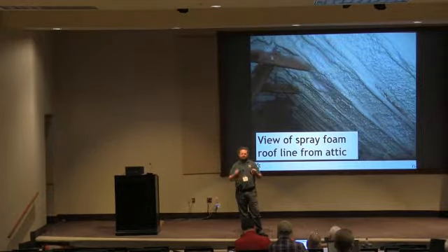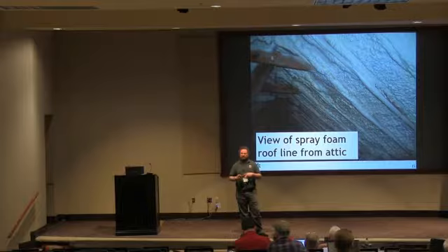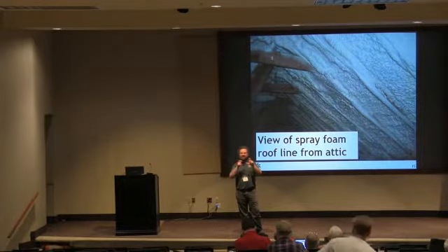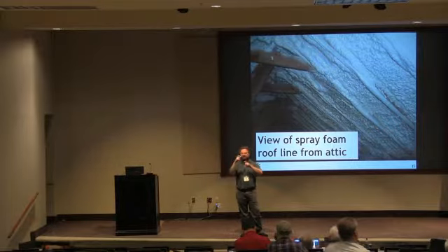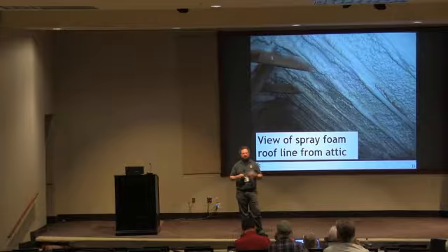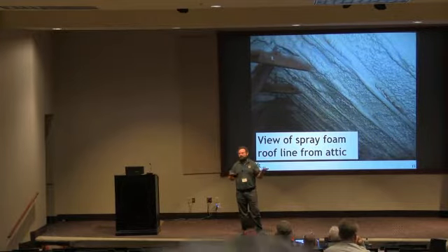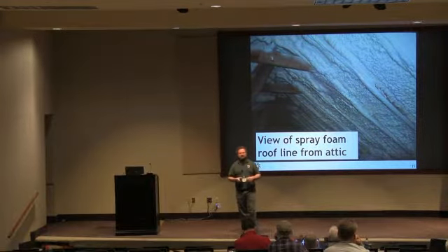And so if you have leakage on the return side of your ducts, it's not as big of an energy penalty anymore. Your duct losses aren't as big because you're running 50-degree air through an R8 insulated duct, but instead of having to be 120 in that attic, it's 95, so you brought down that delta T. So it has a lot of benefits for very little upfront investment in a new home, and it's a very easy retrofit.